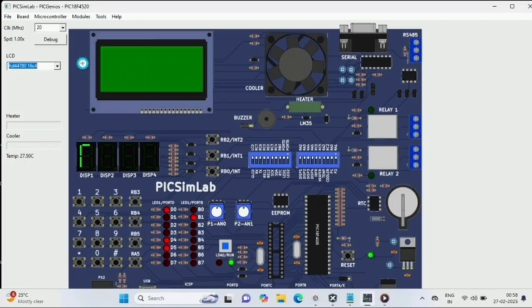First, if you see the top left, that is the green screen area, which is called the LCD display, liquid crystal display. So here this is a 16 by 4 character LCD based on the HD44780 driver. It is used to display system messages, and next, bottom left, the number pad 1 to hashtag. Those are called the matrix keypad. This is a 4 by 4 matrix keypad acting as the user input interface.